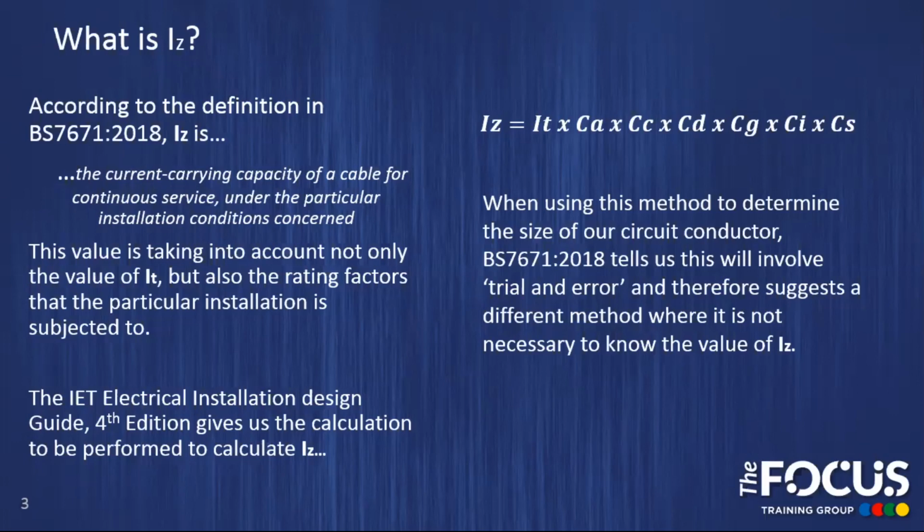Now we can see top right that IZ is equal to IT, which is our tabulated value we looked at on the last slide, times by any of our relevant rating factors. And as we can see, we have rating factors such as ambient temperature, buried in the ground, grouping, thermal insulation. When using this IZ method to determine the size of our circuit conductor, BS 7671 tells us this will involve a certain amount of trial and error, and therefore suggests a different method where it's not necessary to know the value of IZ. We will look at these two methods shortly.